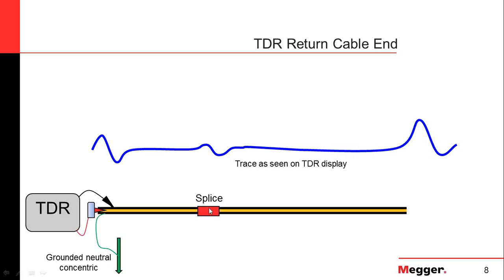If you made the impedance in this splice bad enough, big enough, you might be able to, like if you did comparisons between, say, 15 splices that were all constructed at the same time, and one was just radically bad, you might see the difference. But really the right way to do that is with the partial discharge test. The partial discharge test will nail that bad splice just about every time, whereas the TDR, from a practical point of view, it's not done.